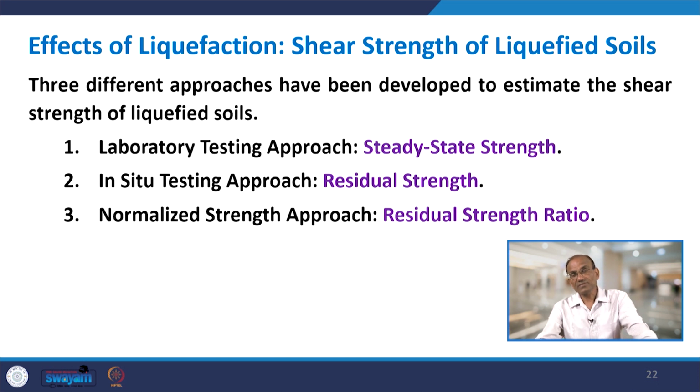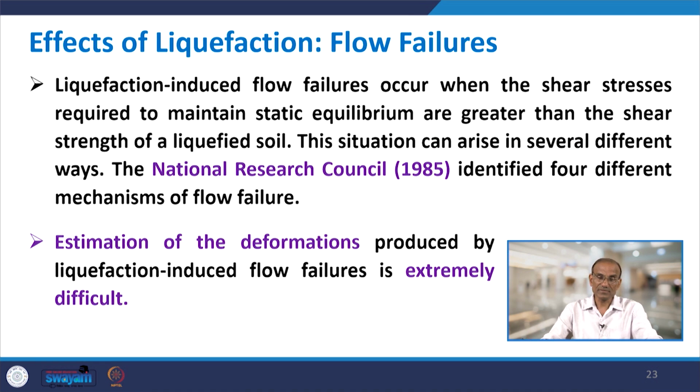Now, continue effects of liquefaction in terms of shear strength of liquefied soils. We want to find out the shear strength of the liquefied soil. So, there are three different approaches that have been developed to estimate the shear strength of liquefied soils. And what are these approaches? One is you test in the laboratory. So, the laboratory testing approach, where steady state strength is assumed, and there could be an in situ testing approach, which is based on the field test, and the residual strength is one of the approaches typically used for in situ testing. Then you could have the normalized strength approach, which is also the residual strength ratio approach. We are going to discuss them one by one.